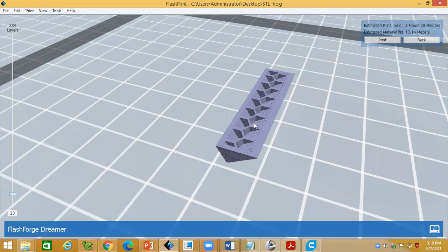Suppose you choose linear, then straight lines come directly. Nowadays you can choose many different types of shapes using different software. And how much infill percentage, how much density is required? I'm choosing 30% in total only; the remaining 70% is hollow. Only 30% material is there inside. Like that, you can choose using the infill percentage values.